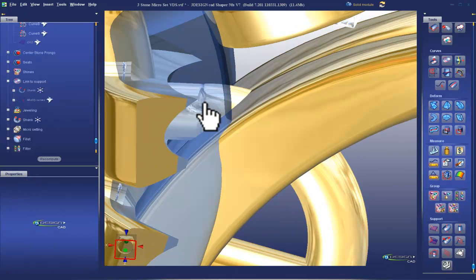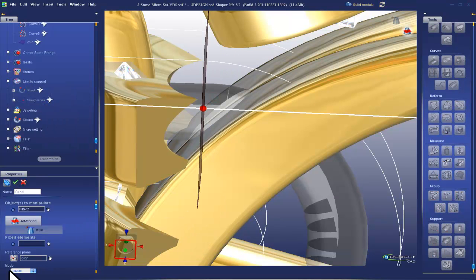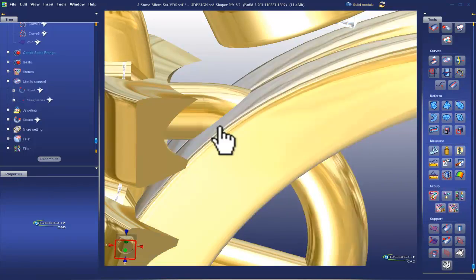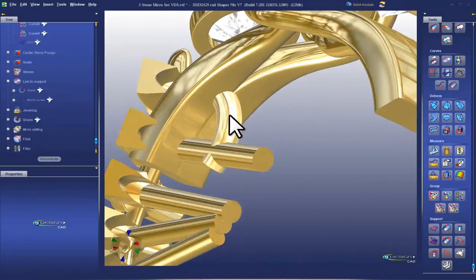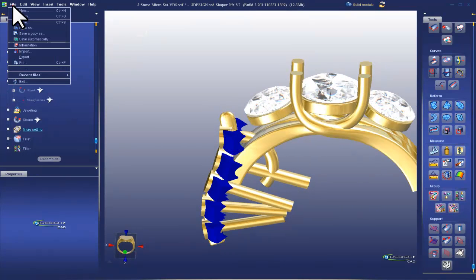Now if you look here, we had some issues with smoothness. I'll hide the shank so you can really see. And the way I adjust that is in break, I minimize the smoothing. It's kind of counterintuitive, but that should increase the smoothness there, and it did. That's going to work out perfect, I think. Yeah, I like that. So let's Boolean all of our cutters together, saving first.